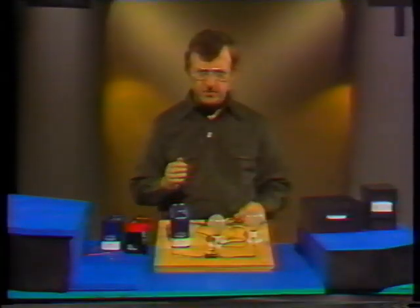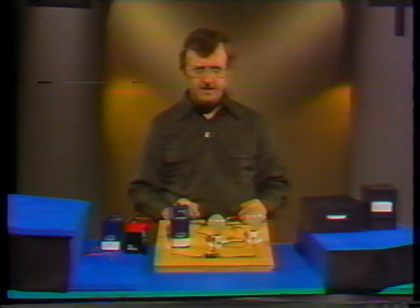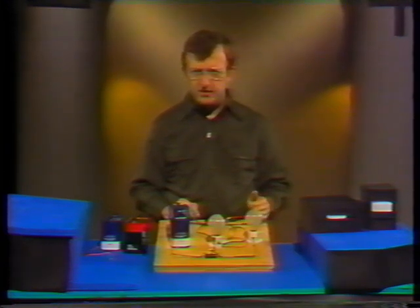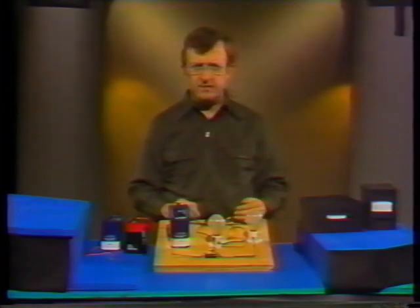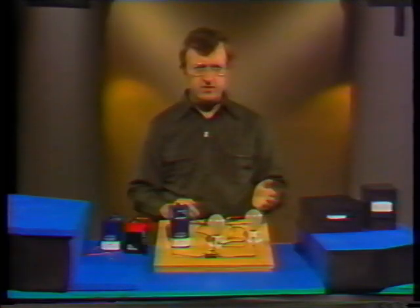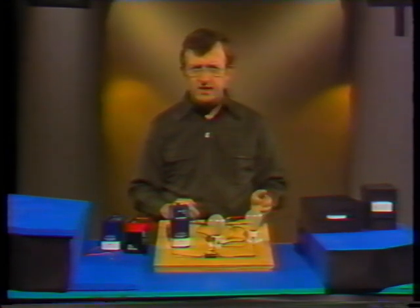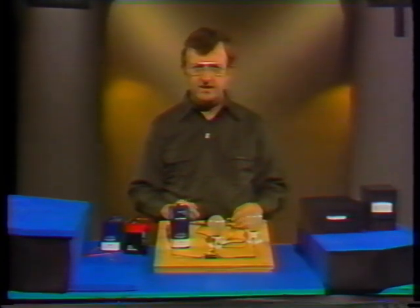Now the readings that you might get during an experiment are not always the exact values that you get by working out the formulas. As you've seen, batteries do not always produce the exact voltages that they should because they're affected by factors like age and amount of use. Light bulbs are also not very accurate resistors. You'll come closer to your predictions if you use resistors with fixed, known resistances.